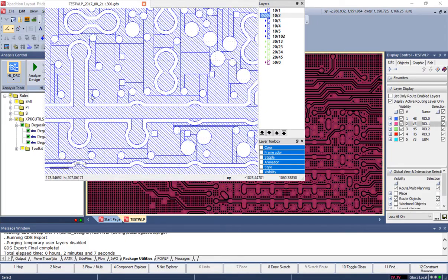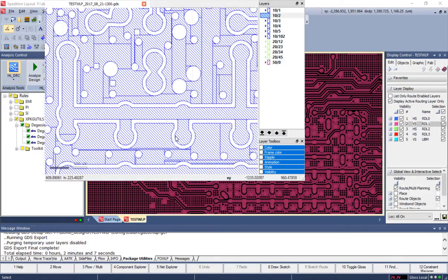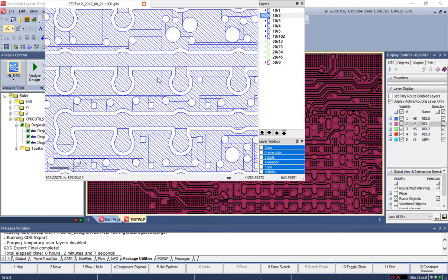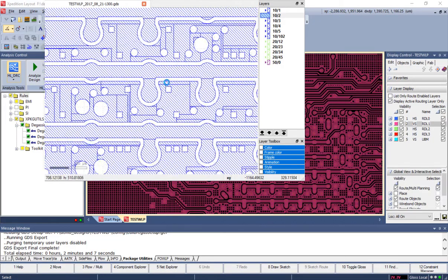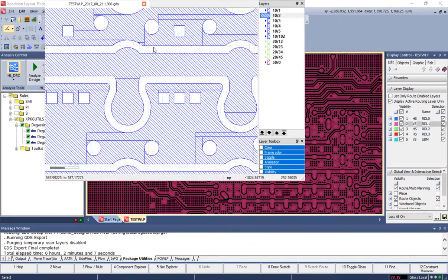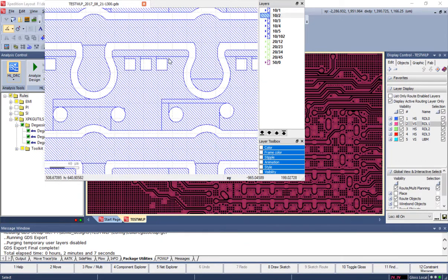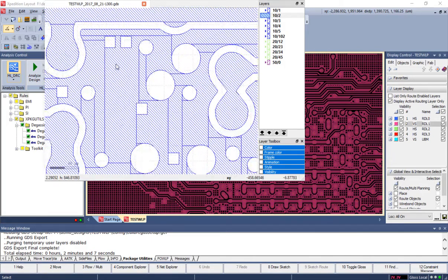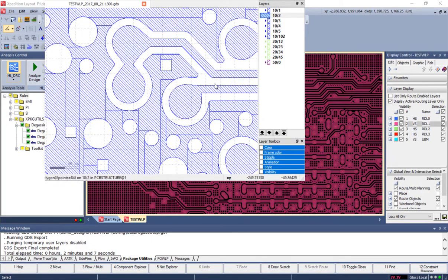Key points here are anywhere there are traces merging into pads with teardrops. These are typical areas where many other CAD systems have severe problems with quality, where jagged edges and acute angles are found, and these lead to thousands upon thousands of false violations.